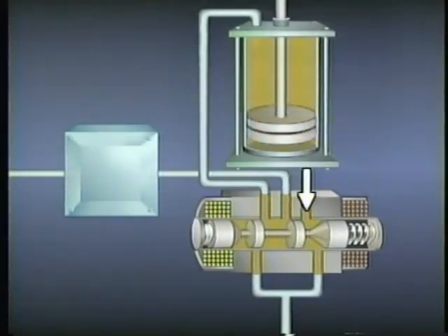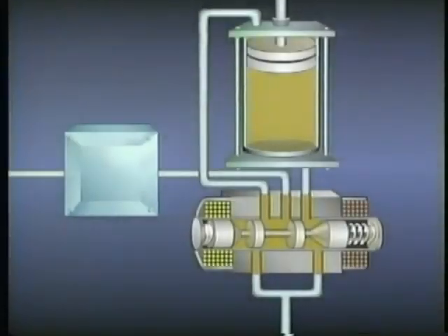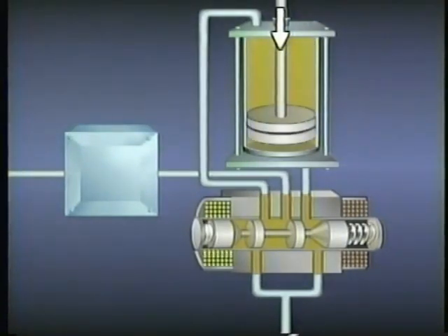The fluid returning from the actuator is controlled only by the movement of the actuator. Because of that, a heavy load that exerts a force in the same direction as actuator movement could cause the piston to move at an uncontrolled speed. This would cause the load on the actuator to run away.